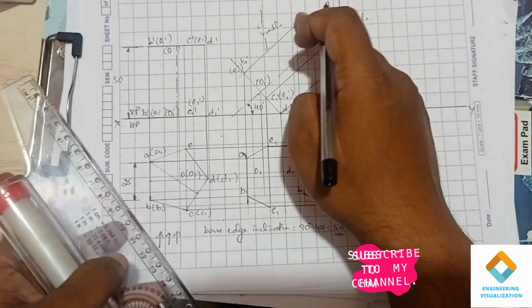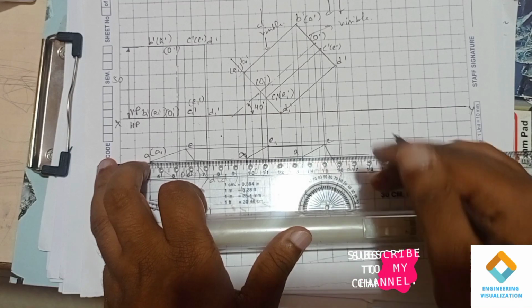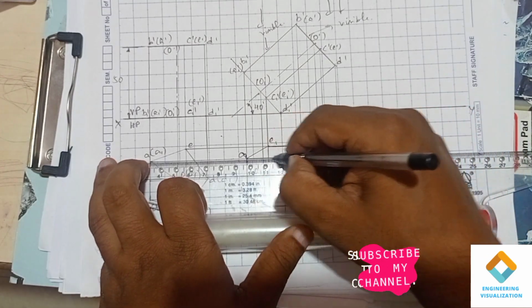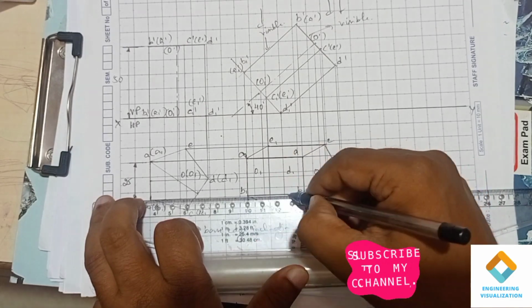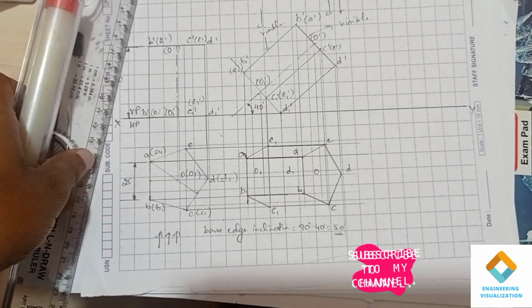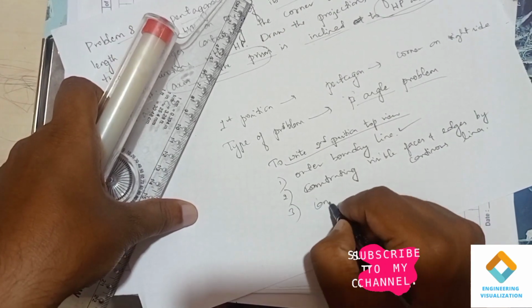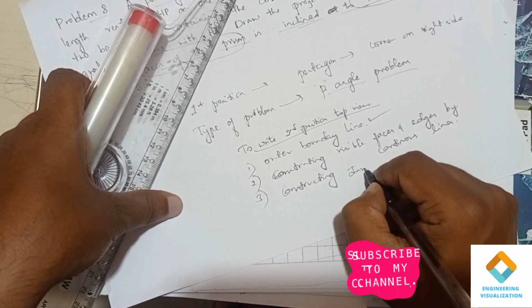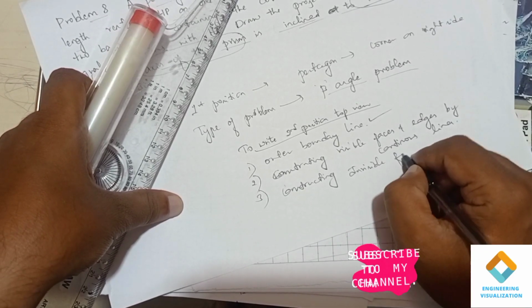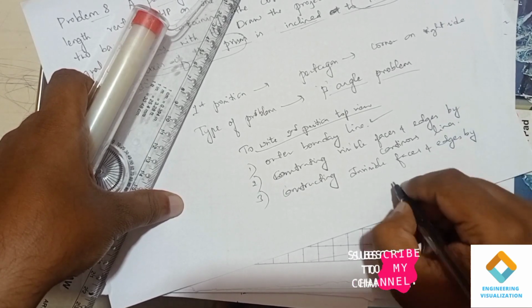And this rectangular face is also visible here, that is A to A1 and B to B1. So this also you connect with a continuous line. Okay, now the third step is writing the hidden faces. So constructing the hidden, or you can say invisible, faces and edges by dashed lines here.